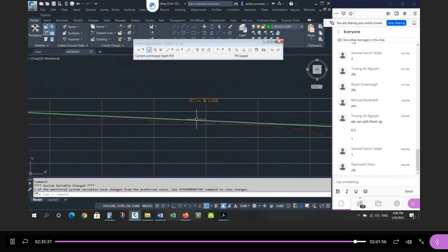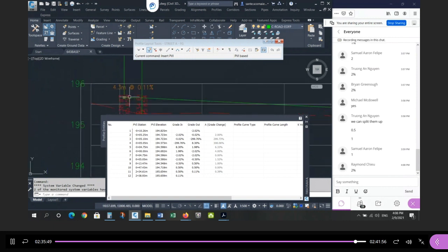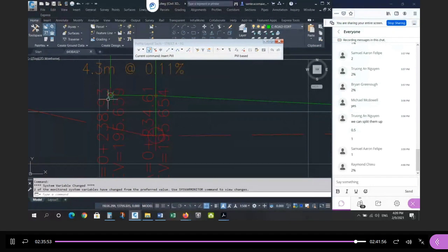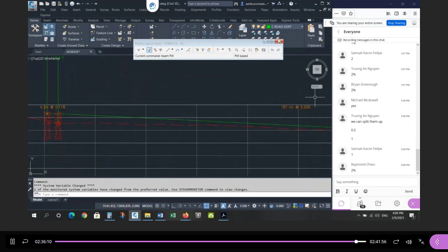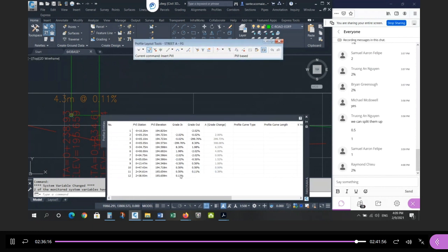But if I make this 0.5%, so now I work in the direction of chainage, right? If I make that one, now I'm in the grayed out column. If I make that 0.5%, now the crown is going to be compromised, right? So now, technically, I need to raise this elevation, which means raise the elevation in the other profile. So this is what I mean about iterative, right? I've done something in the other road, and now I'm trying to use it on this road, and it's not working. Really, I need to use the 0.5% grade. I can't go flatter. And when I get to the edge of pavement, I need to go up at 0.5%. So I want this to be 0.5% at the end.